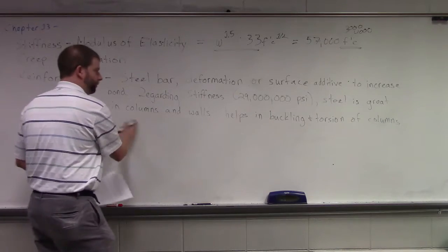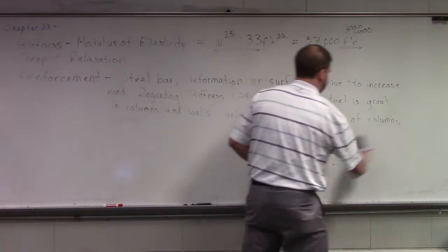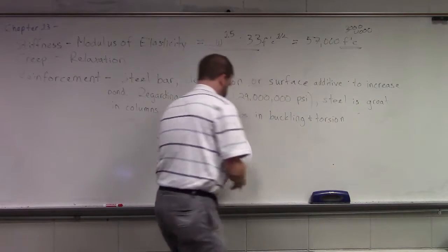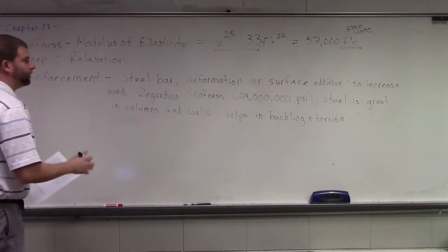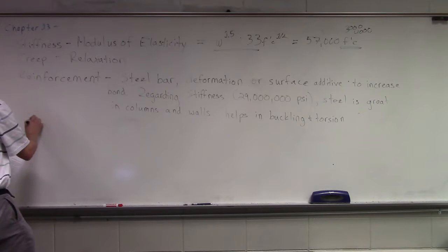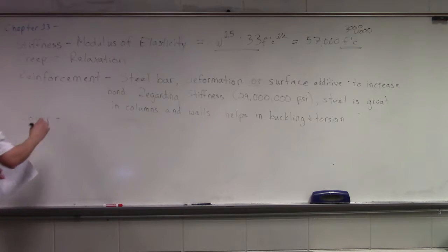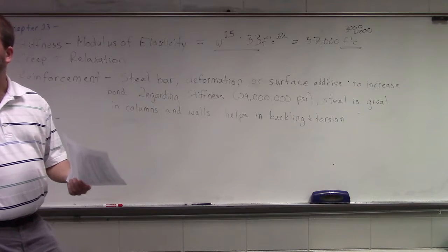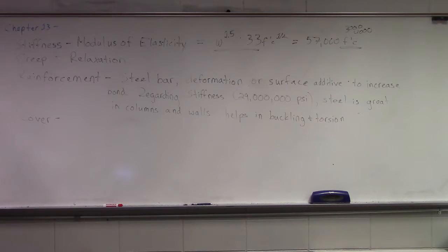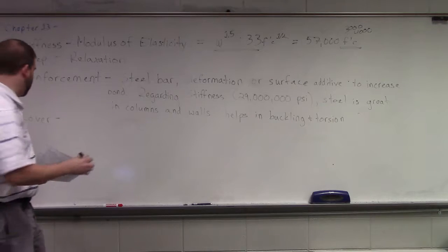I don't need to write columns and walls twice, right? Okay, what else do we want to say? We want to talk about cover. What is cover? What are we talking about when we say cover? Cover from the elements? We need to protect our steel, right? What happens to our steel if we don't provide protection? Rust. It's going to start corroding, right? It's going to oxidize.